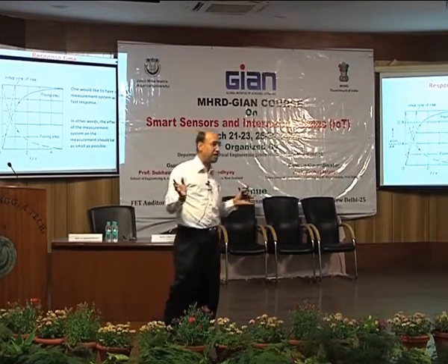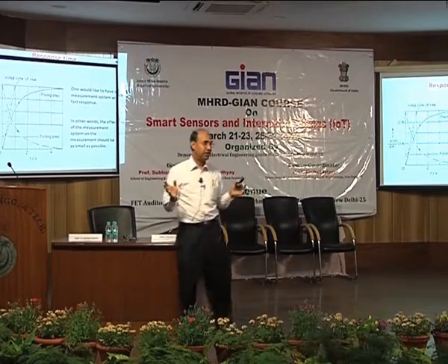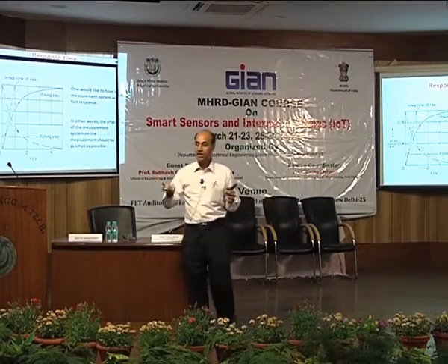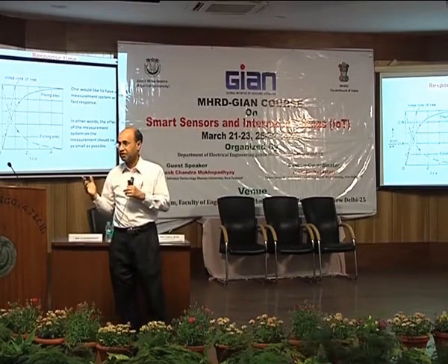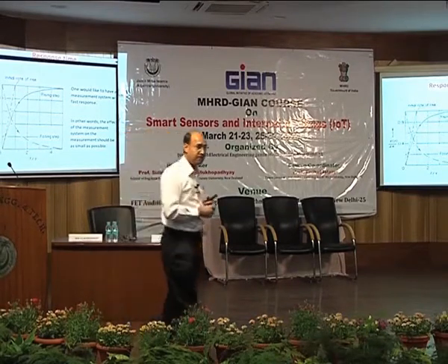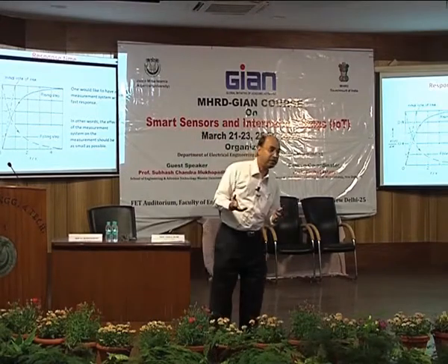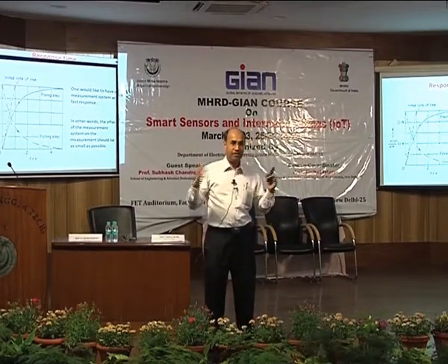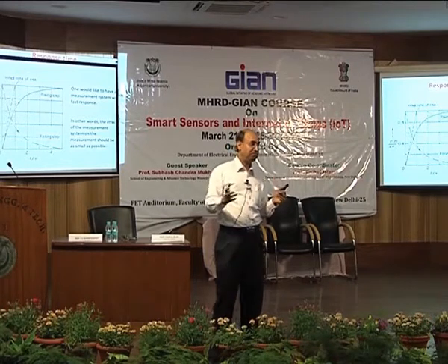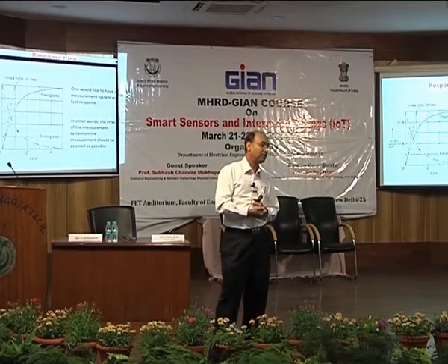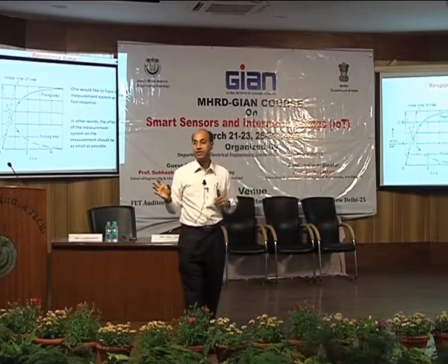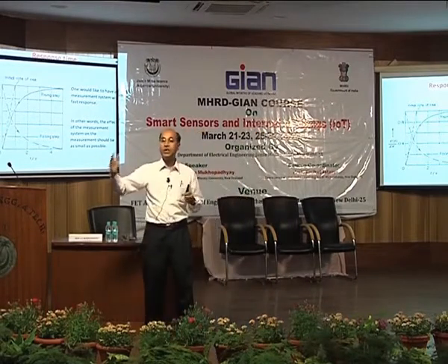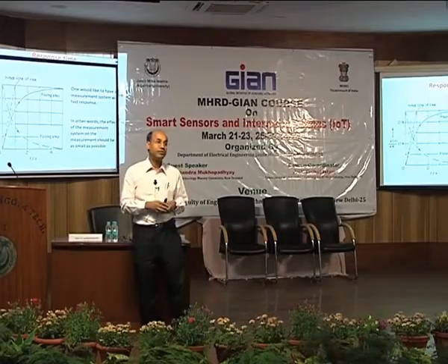If you do not concern yourself about accuracy, you can say the best is 3 time constants, where you reach 95%. Otherwise, you go for 4 time constants, you reach 98%. Or if you have enough time, go for 5 time constants, you reach 99%. But you never ever reach 100%, because 100% you reach ideally when the time is infinite.